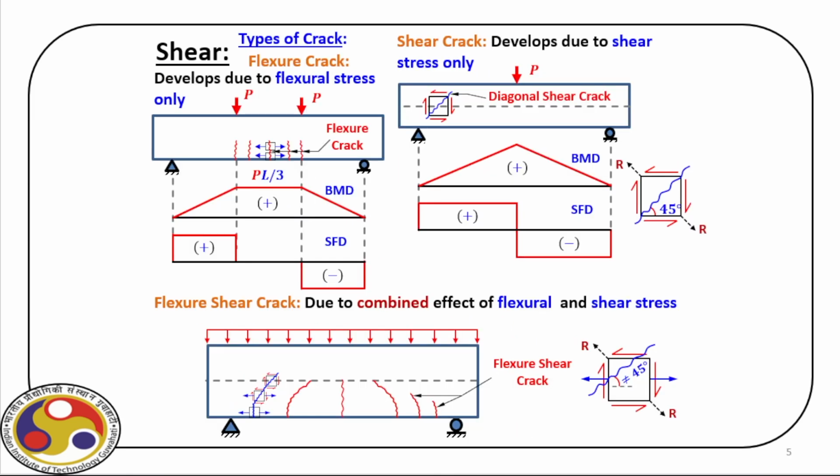Now the question is, why are these types of shear reinforcements provided? For that, let us just quickly see the pure bending case. As you can see, in this case we have this two-point loading at the quarter points. Then for that we have this region which is under pure bending. Now if you look at the cracks, obviously if you take a small section here, it is under axial tension, as you can see here, and therefore tensile cracks appear.